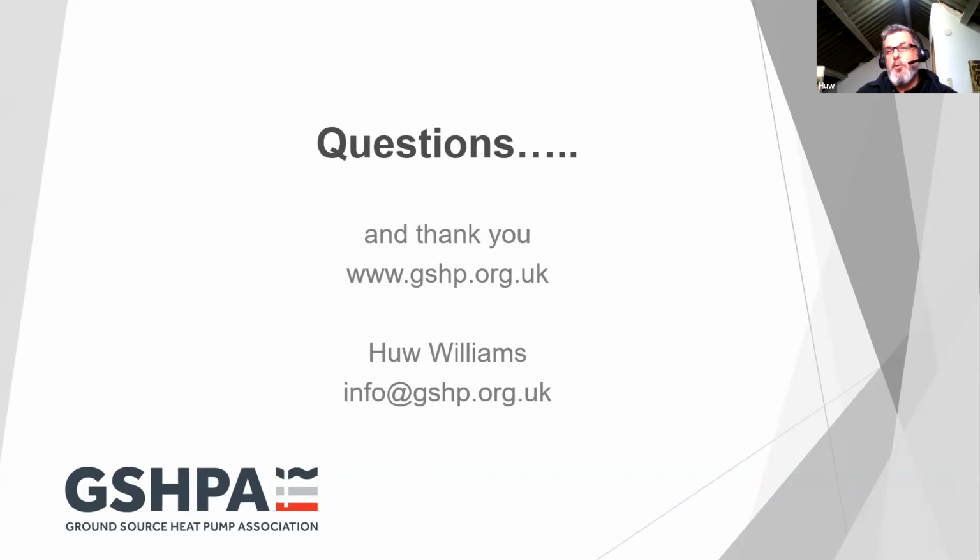And it's not just, as I said, this is a quick run through the highlights, but that's a really good point, Ian, that we hope that our model can optimize the operation of the ground source heat pump system as well. Perhaps we can have higher flow rates, change the delta Ts. Especially when we've got multiple borehole systems, more than one abstraction, more than one injection borehole, how we abstract from those and inject may not be just an even split between them. It may well be that we can optimize the operation, reduce pumping costs, reduce spacing, as you said, all sorts of things.